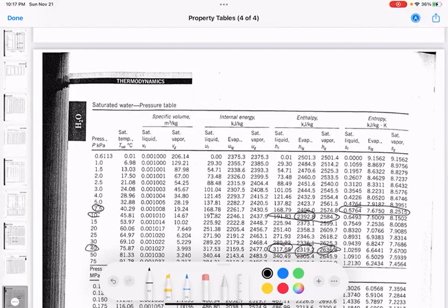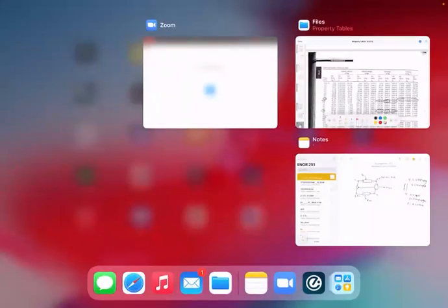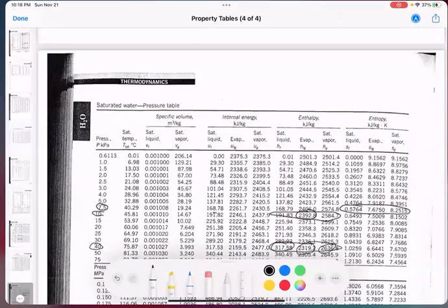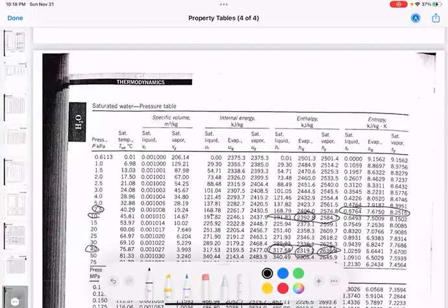So 0.5764 plus 0.6475, which is the quality, times the change, I'm getting 5.753 as the entropy. Does that match up? Very closely. We have 5.7432 there and 5.753, so we're within some reasonable value.